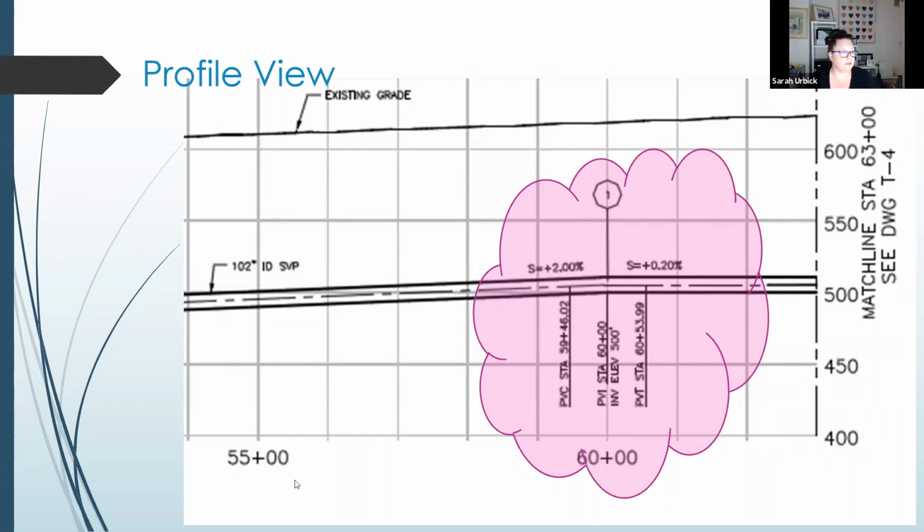Okay. So we have a point of vertical curve, our starting point, we're given the stationing, we're given a slope, an initial slope coming in. That would be equivalent to our radius and our angle, right? Gives us 2 dimensions. How far am I going? And then what's my vertical component?